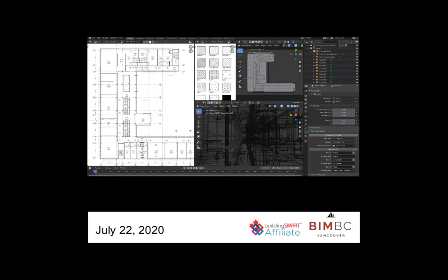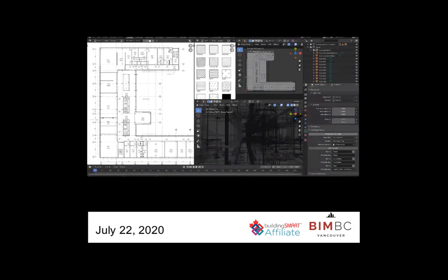So Blender Bim is still bare bones, but as you can see, we can produce certain types of output with it. And we have produced output right down to fabrication level drawings directly in Blender, again from the IFC file of a door. You can see here how that tag actually relates back to an IFC space. And in this case, it's extracting 3 pieces of information from that IFC space, and so on and so forth.